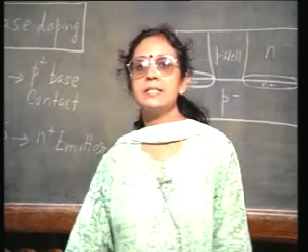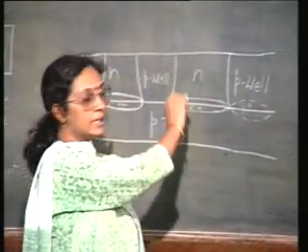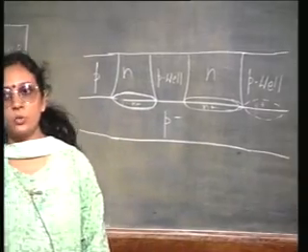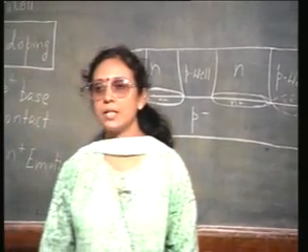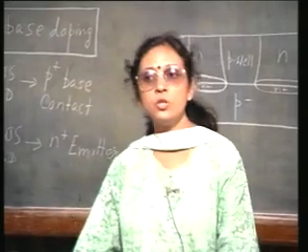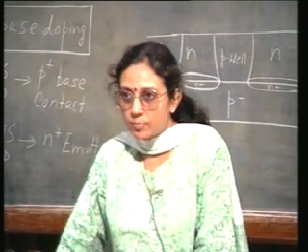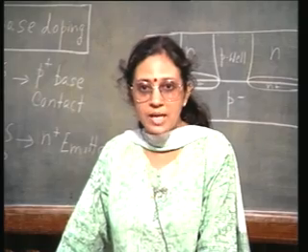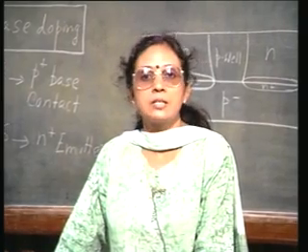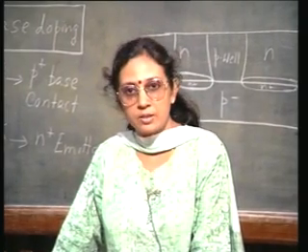So, we added the buried layer and the epitaxy, that is the retrograde well structure. Basically we killed two birds with one stone. We prevented the latch up problem for the CMOS as well as reduced the collector resistance problem of the NPN transistor.